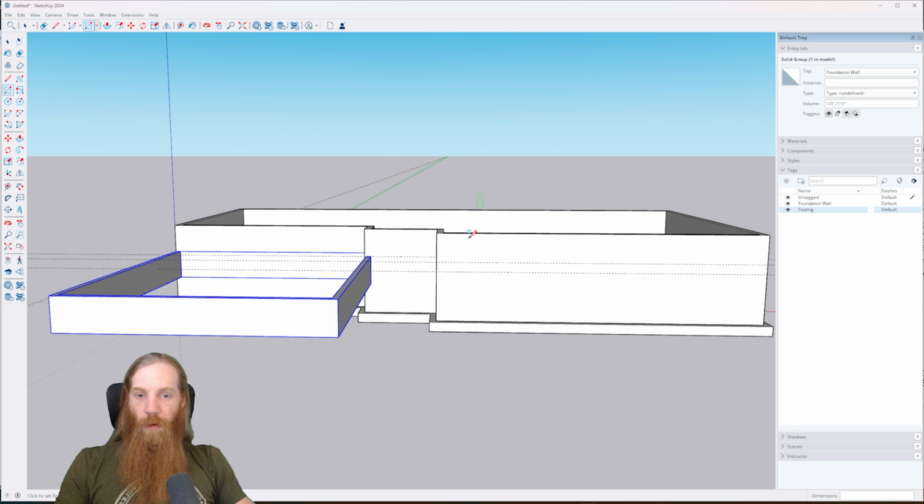Also, when rain or whatever water coming off the roof splashes off the ground, it's going to be splashing up onto concrete rather than your siding. So again, you're just improving the longevity of your siding and trim in that case. So I like having basement foundations that are not buried all the way to ground level. We want to leave, I would say for my area, typically at least 3 feet of foundation above grade would be ideal. 3 or 4 feet, I think, works best. If you could go 5 feet, that's probably even better, right?